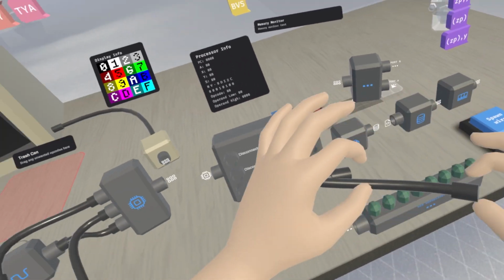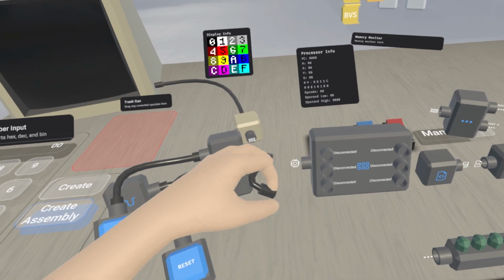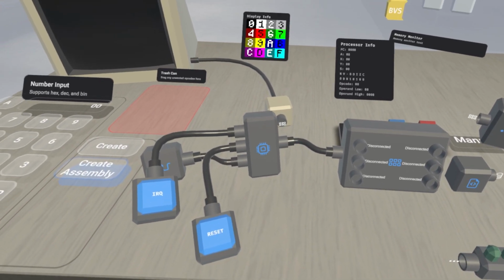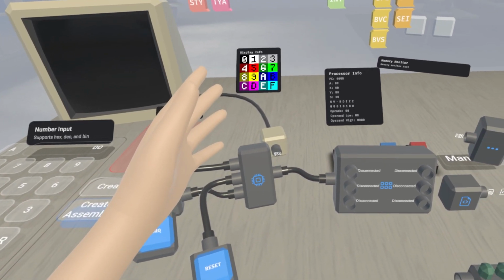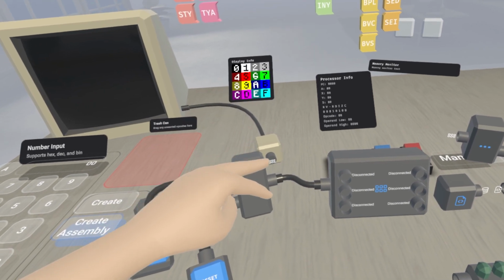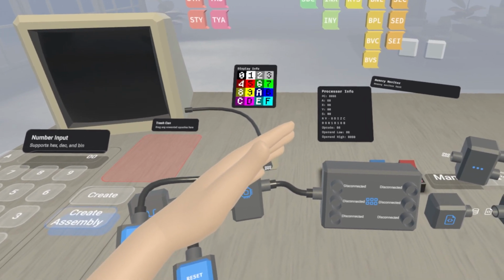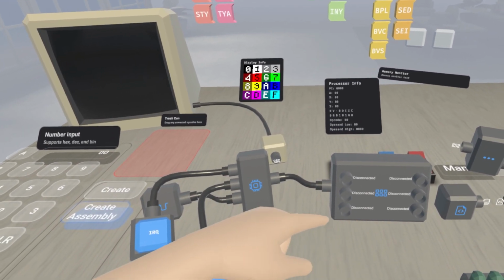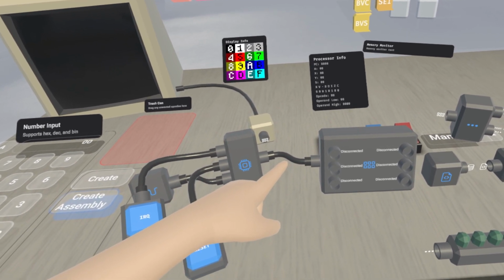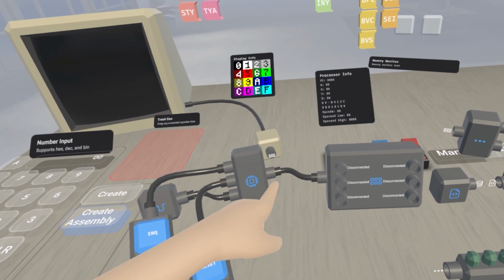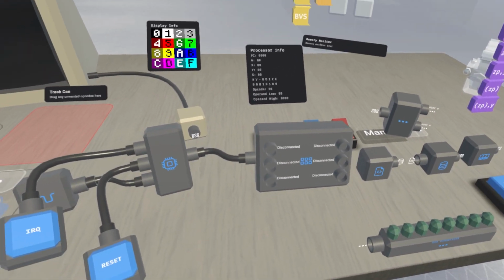But we're going to connect it to the computer using a single cable, and you might find that a little bit interesting if you know anything about the 6502, because it uses both an address bus and a data bus. The address bus is 16-bit, the data bus is 8-bit, and those two things are what actually connect to every component. So this is not entirely the most faithful recreation of how this works, especially considering that we just have one big wire right here. But the point of this is to basically separate out that 16-bit address bus and 8-bit data bus into a ton of different ports that each of our devices can connect to.